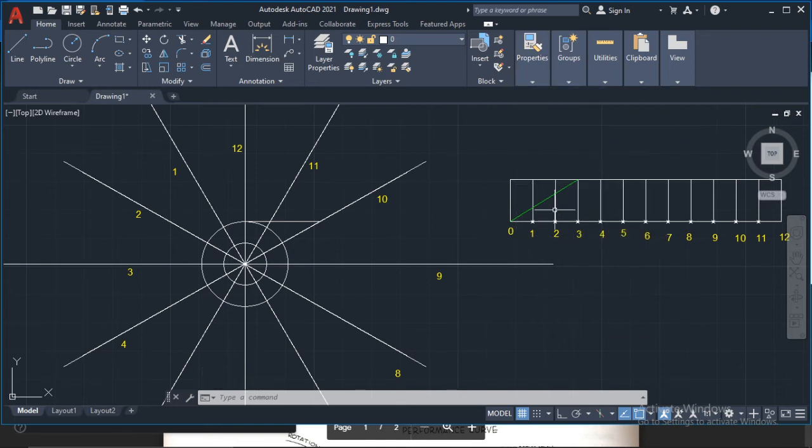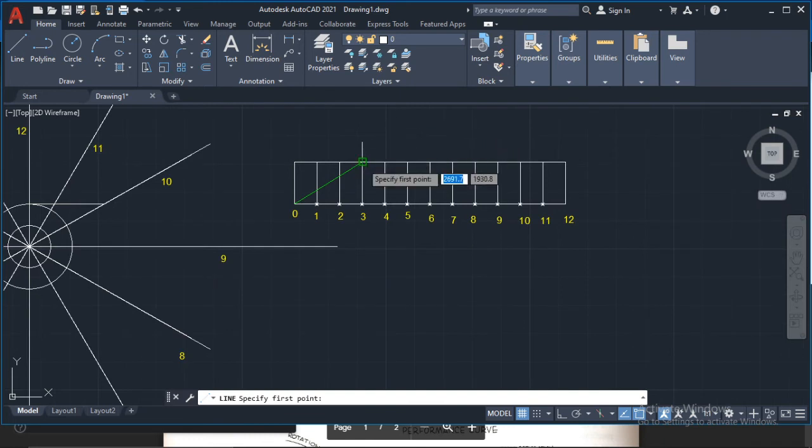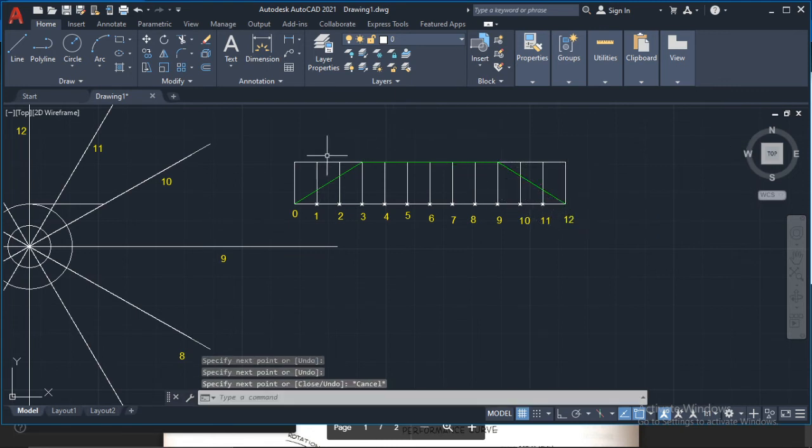So it goes up to 90 degrees and then it dwells for 180 degrees: 30, 60, 90, 120, 150, 180. So right here, and then it falls for the next 90 degrees. So that's the performance diagram here.